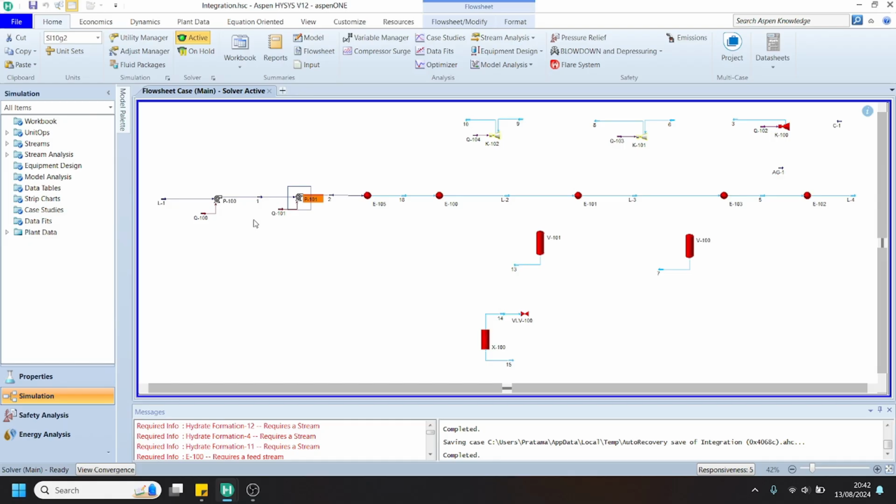Practically, between these two pumps, the LP and HP pump, there is a recondenser that is used to cool down the BOG using the LNG from the storage, or absorb the boil-off gas which is produced due to heat ingress into our system. And the recondenser can be used to mitigate or prevent cavitation of this high pressure pump, or let's say we can use the recondenser as the pump suction drum.